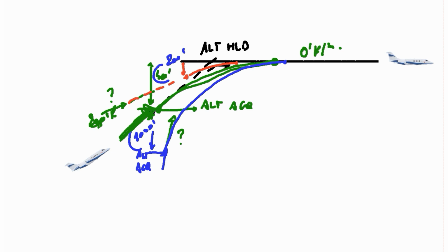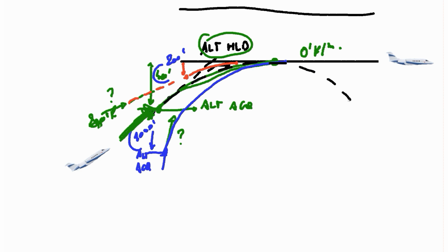So what happens if I change the selected altitude during the altitude acquisition? Well, if I move this selected altitude to a new line, so I put the altitude there. Now what happens is that this circle that I started drawing is not applicable anymore, because this circle would not bring to any selected altitude, given the fact that this white line here is not existing anymore. So I should cancel this black line here, sorry. This black line here is not existing anymore.